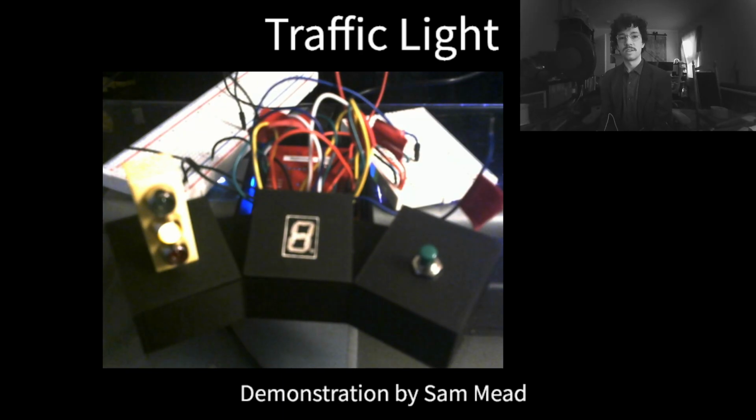So for all other operations involving the pedestrian, we are essentially just going to be setting a flag to change what happens in the red state. In the red state without any input, we're not going to have a walk sign. So it's just going to go through the 10 seconds and then loop back to green.